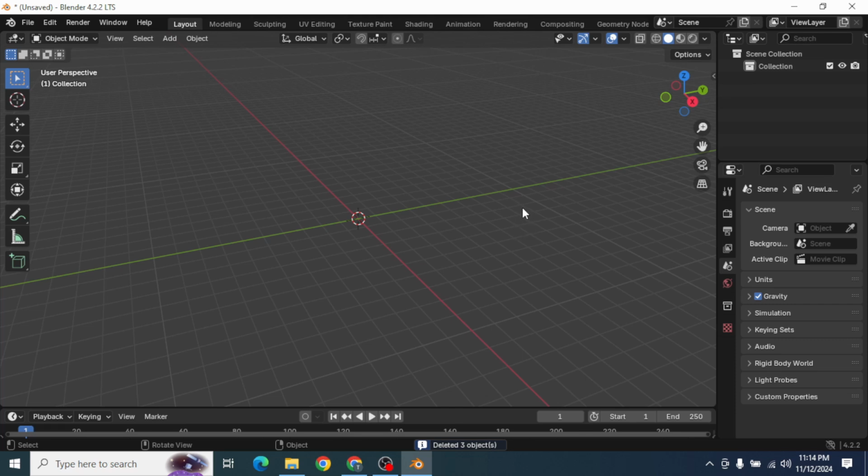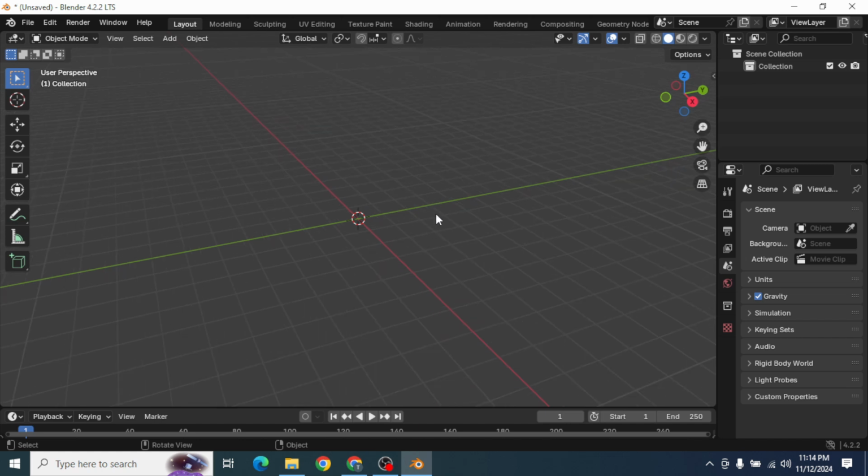To make a ladder, when you notice a ladder, the ladder has two parts. One is the side beam and another part is the supporting stick. That is, steps, side beam and steps. We are going to make the side beam using a cube and the supporting steps using a cylinder. To make the side beam, we are going to add a cube.